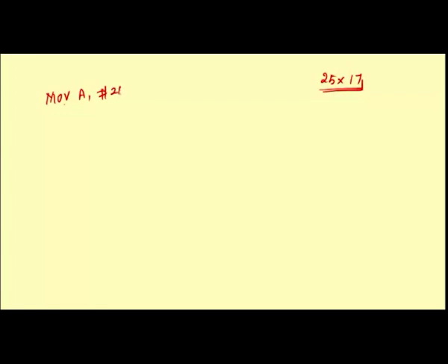The other I load in one of the registers, so 17. This indicates that 25 is going to be added 17 times. Either you can initialize it in the accumulator, or use the R1 register for consecutive addition. These two are the data initialization.